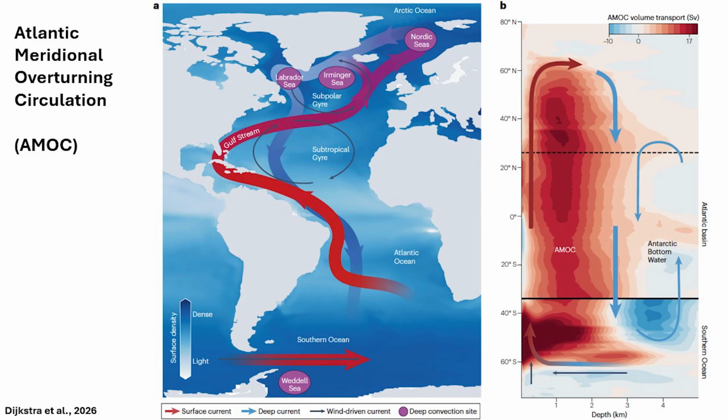And then you do that at every single depth level, so below the surface, all the way down to the ocean bottom. And you cumulatively sum that velocity. And you come up with a stream function. And basically what you're doing is you're collapsing this three-dimensional ocean circulation into two dimensions. And the reason you want to do that is because it simplifies the system. And so instead of measuring all these various currents, you can actually collapse the system and measure a few critical spots.